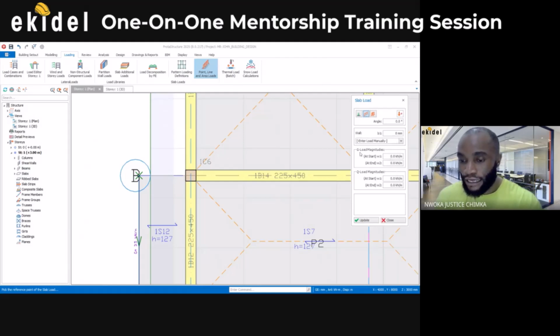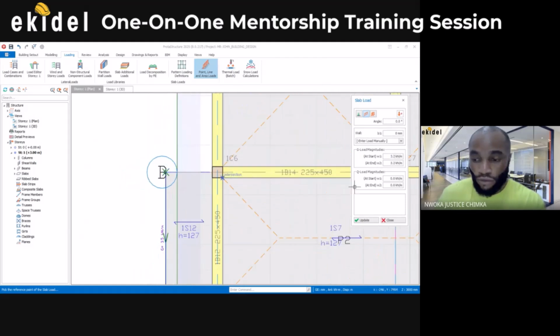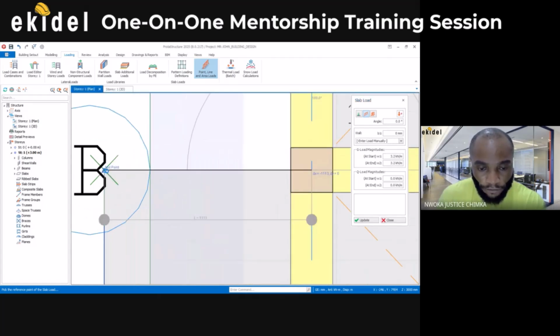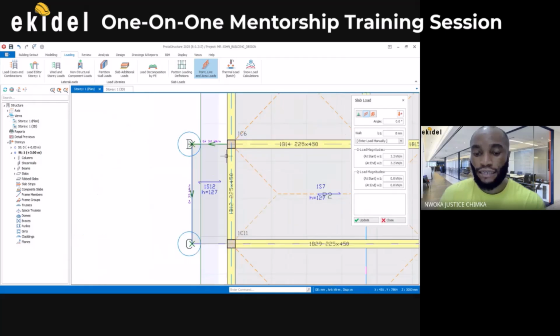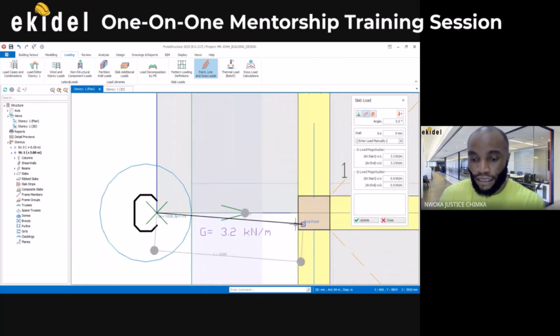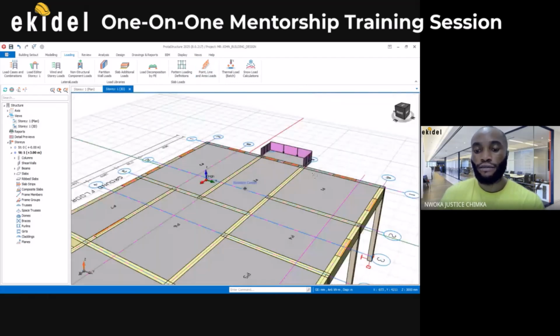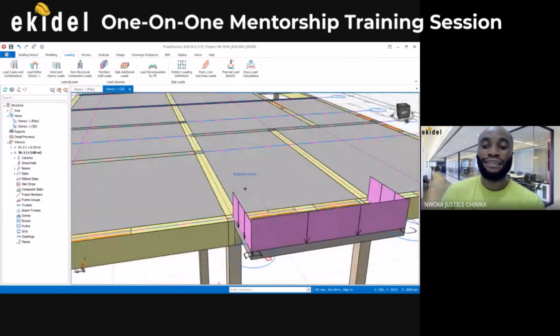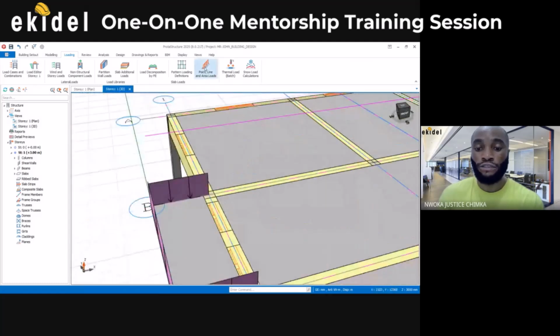They say add the value. I'll put it under dead load 3.2. That's what you were using before. Now I'll click on this point, and then click on this last point here. You can see the load is not added. I'll come again here, click this first point, and then the last point where the load is to be added. You can see our load. If I go to my 3D view now, you can see the load is there. Can you see that? Yes. Correct. So that's how to add line load. You can just add line load using this method.